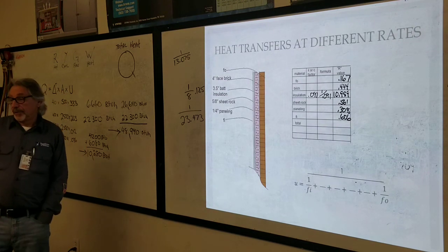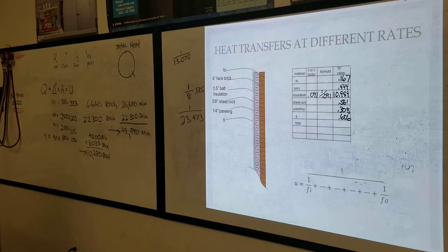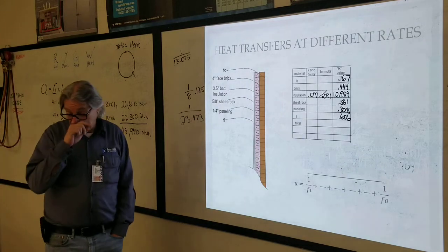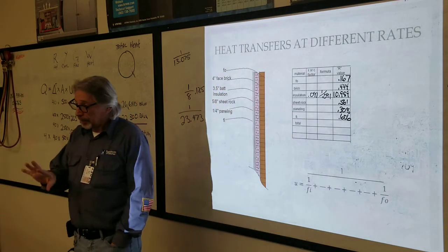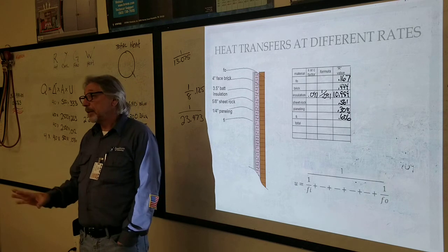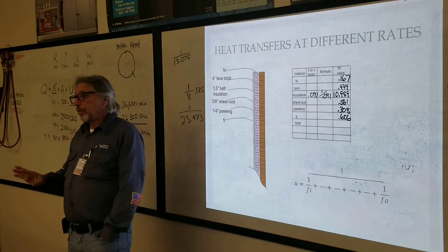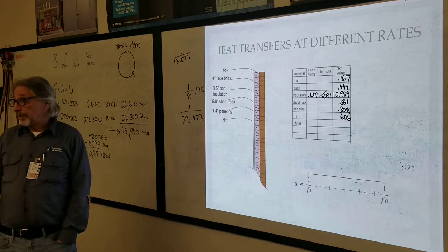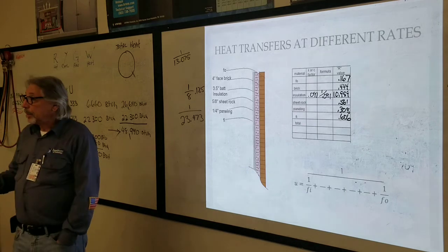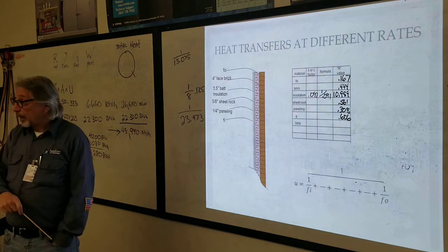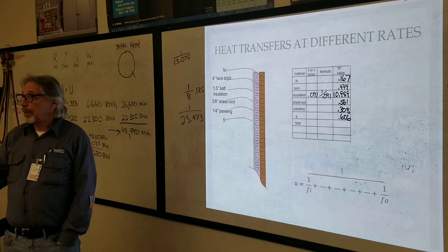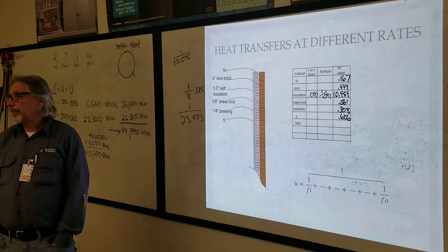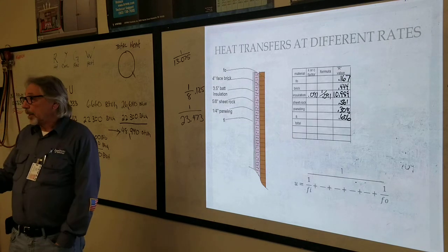This is the way it used to be done. This is only one way to do a heat load. You're gonna end up learning about four different ways. When I was working in the office doing bids, if I did a heat load, I'd always do it again another way, to make sure that I'm right on track.